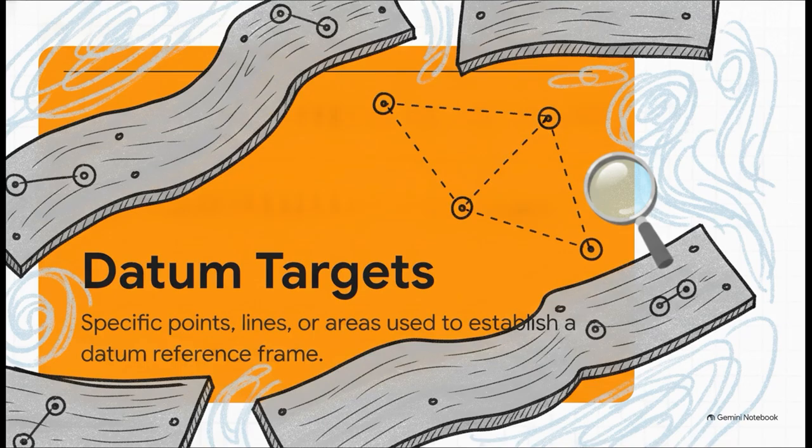Full surface datums completely fail because as-welded surfaces are almost never flat enough to ensure reliable contact. So instead of trying to use an entire wavy, warped face as your foundation, you define specific contact points, lines, or small areas. This lets you create a highly repeatable, rock-solid coordinate system straight out of a bumpy, raw surface.